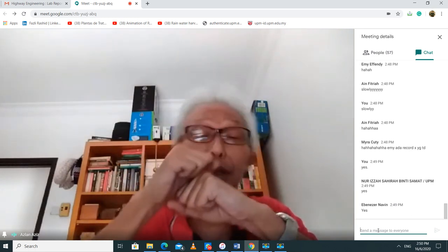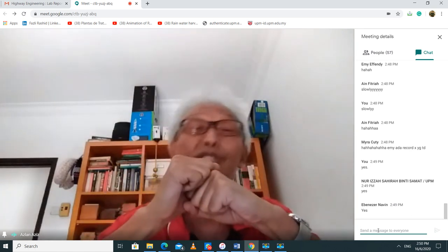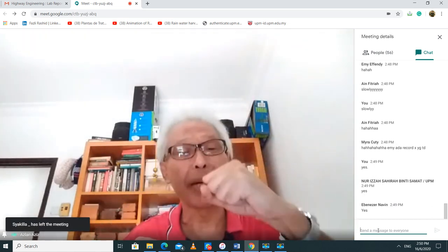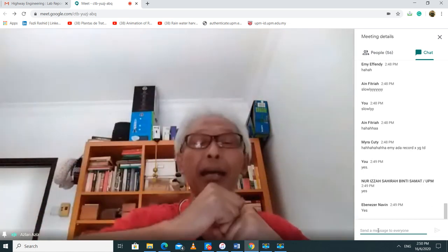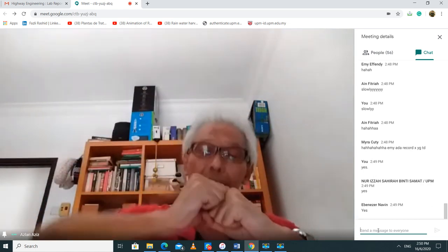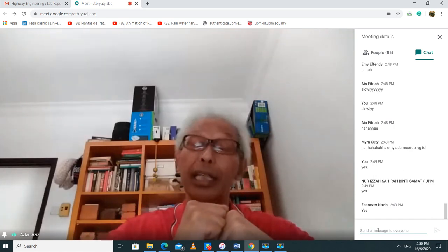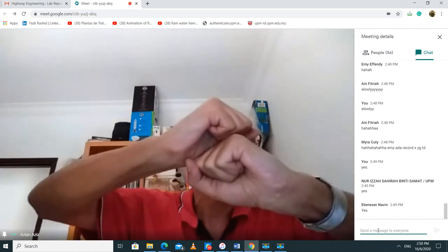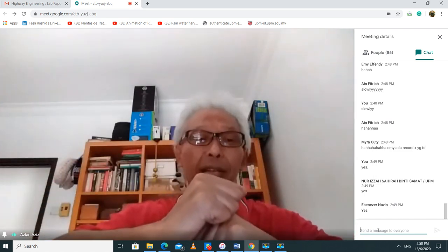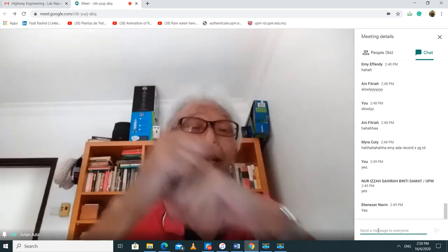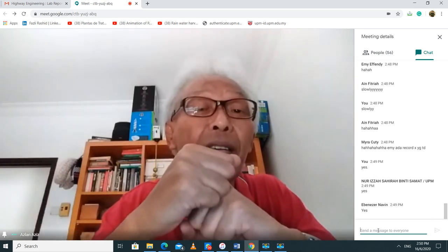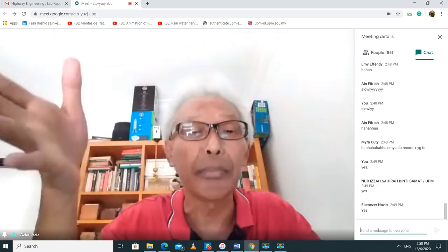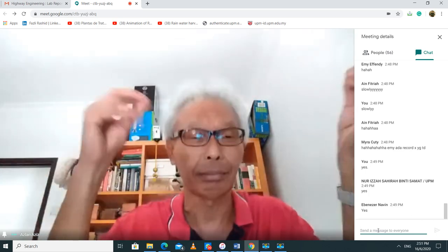Particles. I've already explained this many years ago, at least 2 semesters ago to you. Now I'm reminding you that I have a particle, I have another particle. If I apply a load to this soil, they will feel crushed, but they need to move over each other because I'm compressing them. They need to move, so as they move, they are building friction over each other. That is the thing that is giving you the phi, angle of internal friction. That's what is meant by internal friction. Okay?